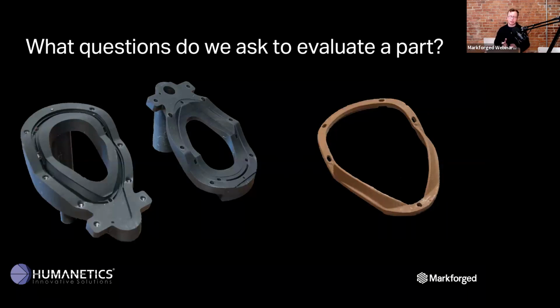We're getting some great responses in. Basically these questions are really about what we need to ask. What is its failure behavior? How would we want a part like this to fail? There's another loading case here where this part gets bolted together, so that's an important consideration. We need to think about that with each of these applications, because that's how we need to think about each part.